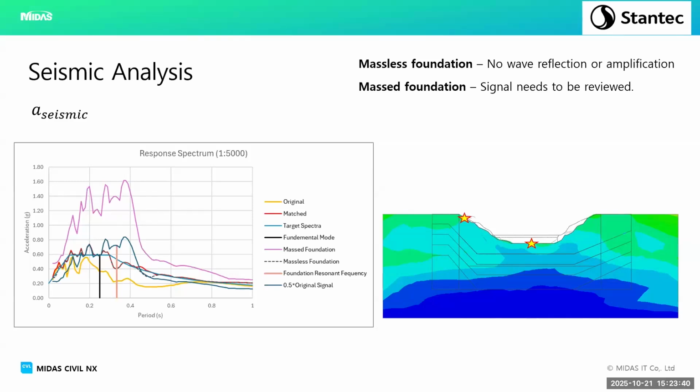And for dynamic amplification, generally you'd want to take 0.7 of the forcing frequency and 1.4 times the forcing period of the structure. If it's outside that band, it doesn't have as big an influence. So you could use that as a rule of thumb.